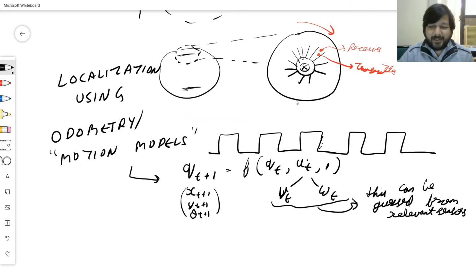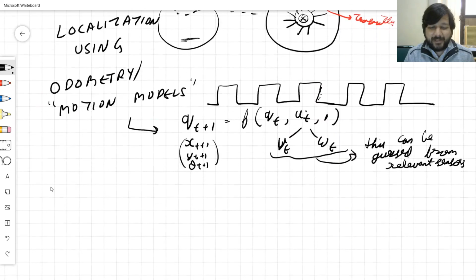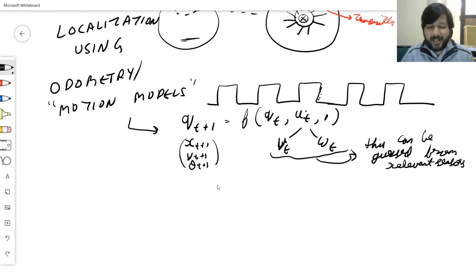These are specifically called the incremental encoders. This is not the one you use with the manipulators. With the manipulators, we use the absolute encoder. So that's a manipulator. And this is the same motor that is over here. Take it like the same wheel over here. And there also there is an encoder.